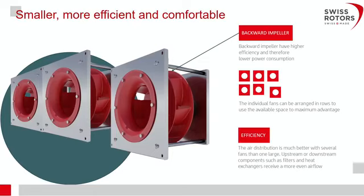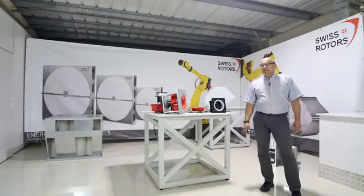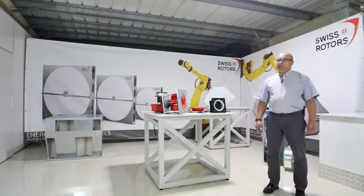All of the fans could be used. In that kind of solution, we have a very high efficiency, higher than normal. The installation length inside the air handling unit is much shorter, because the fan wall is very short. We don't need a frame for the belt, or even any belts.